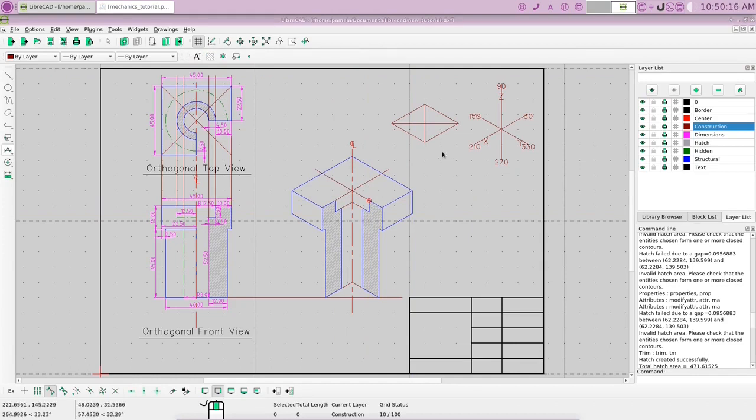So next thing we're going to do is select all of these lines, which we can easily do by clicking the mouse and dragging backwards. And there you go. Now we're going to go to copy move, and we're going to snap on intersection. And if you read down here, it says specify a reference point. Well, that will be the center.